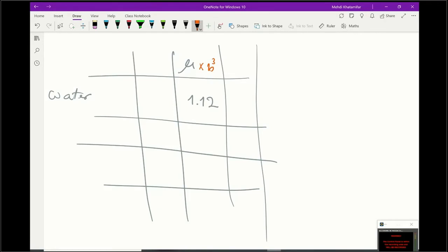Don't worry, even third year students make this mistake. When they read it, they say, okay, I need to multiply viscosity by 10 power 3. No, it says I already multiplied the value inside here by 10 power 3, so it must be 10 power minus 3 there. As an engineer, we expect you to know the range of numbers. If it's 10 power 3, it's more viscous than honey, so it won't make sense. It should be a very small number, so don't make those types of mistakes. Sorry. So let's go back to the question.